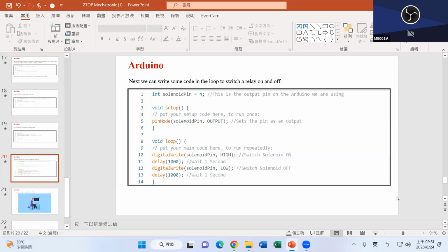But this has four relays, and it actually depends on how many air pumps you need to use. Each relay corresponds to one air pump. So if you use three air pumps, you have to use three relays. So I can control each air pump independently? Independently, yes, or at the same time. The reason it has four relays is to save space. So we can do up to four air pumps. It depends on your design.